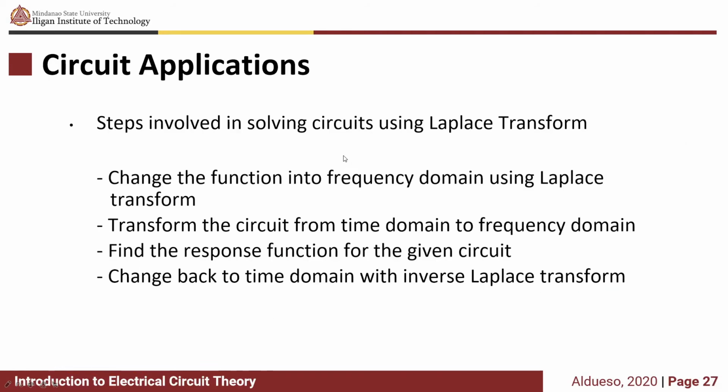So now we'll proceed to circuit applications. Here are some steps involved in solving circuits using Laplace transform. First, change the function into frequency domain using Laplace transform. Second, transform the circuit from time domain to frequency domain. Then, find the response function for the given circuit. Then lastly, change back to time domain with inverse Laplace transform.